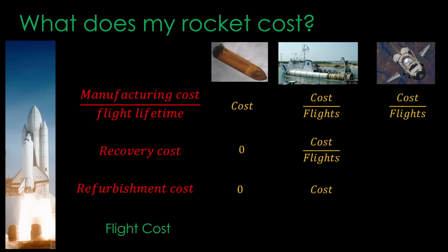The shuttle orbiter was reusable, so the construction cost, hard to nail down, but $1 billion is in the right ballpark, is spread across an average of 27 flights for the 5 orbiters built, so a little under $40 million per flight. I'm going to call the recovery cost minimal since it didn't have any expensive marine assets, though there was a dedicated 747 to fly it home when it had to land in California because of weather. And there was a refurbishment cost before it could fly again, which was very high for Shuttle. It's better to call the process remanufacturing rather than refurbishment.